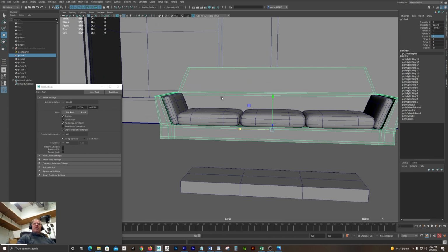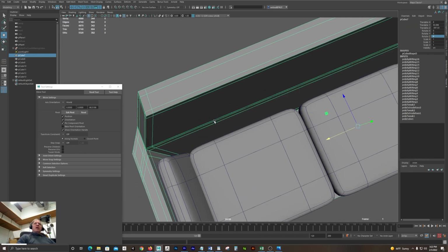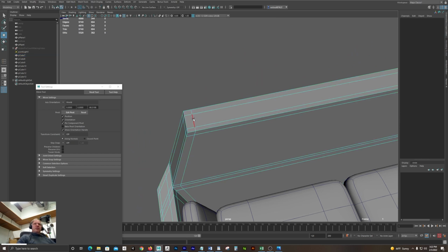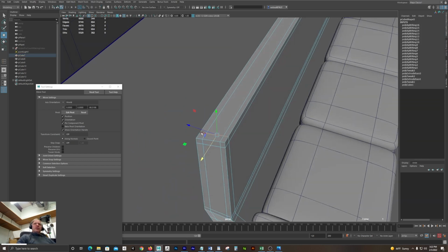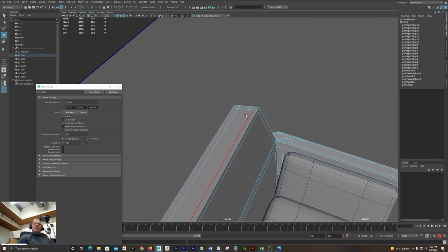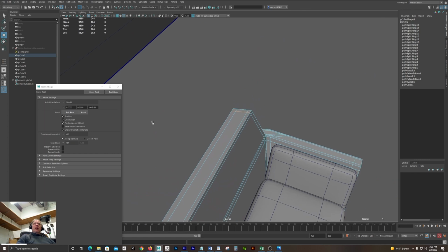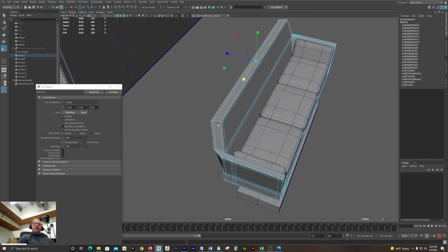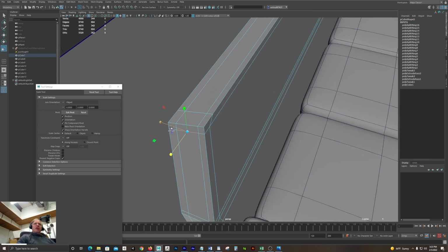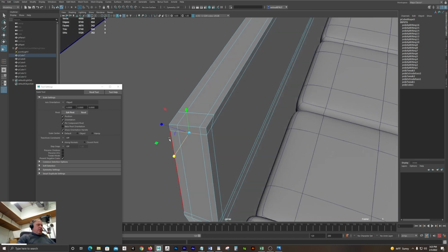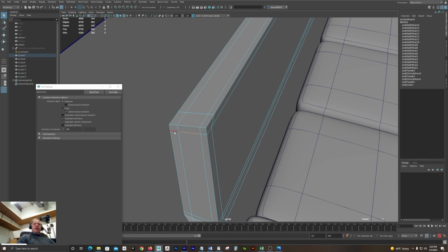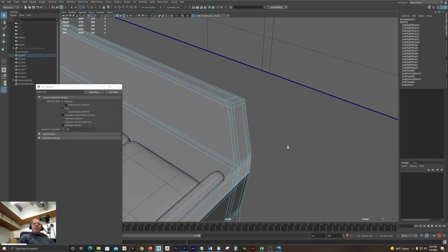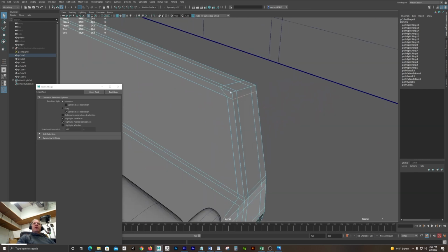Let's go to the rough. And F10 to deal with these edges. I want just these three on the top and their mates over here. And to move two sets of edges, of course, I can just scale them. R to scale, bring it in. And I want the same over here. So I'm taking away the support of this edge loop that holds this edge, and that's going to give me more rounding in the smooth. 1, 2, 3.